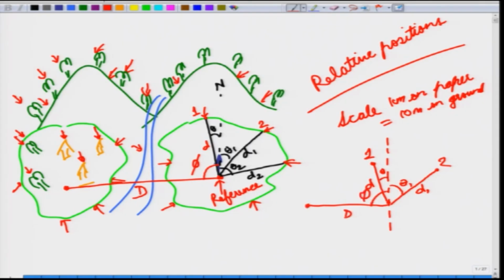So, you get the second reference on the piece of paper and now you can start plotting the points that are being measured from the second reference. So, the first stage in surveying is to have a general view, so that you can figure out what is going to be your reference point and if you require multiple reference points, what will they be.